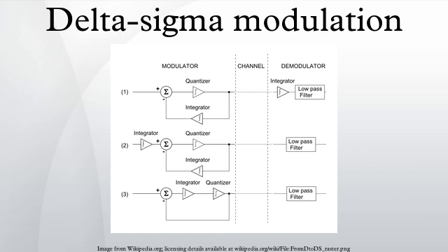Each pulse is made up of a step up followed after a short interval by a step down. It is possible, even in the presence of electronic noise, to recover the timing of these steps and from that regenerate the transmitted pulse stream almost noiselessly. Then the accuracy of the transmission process reduces to the accuracy with which the transmitted pulse stream represents the input waveform.